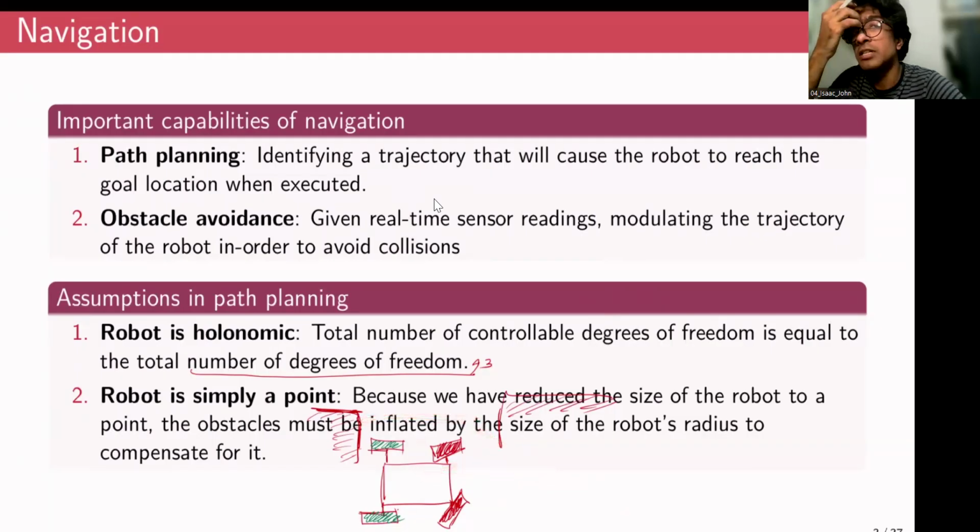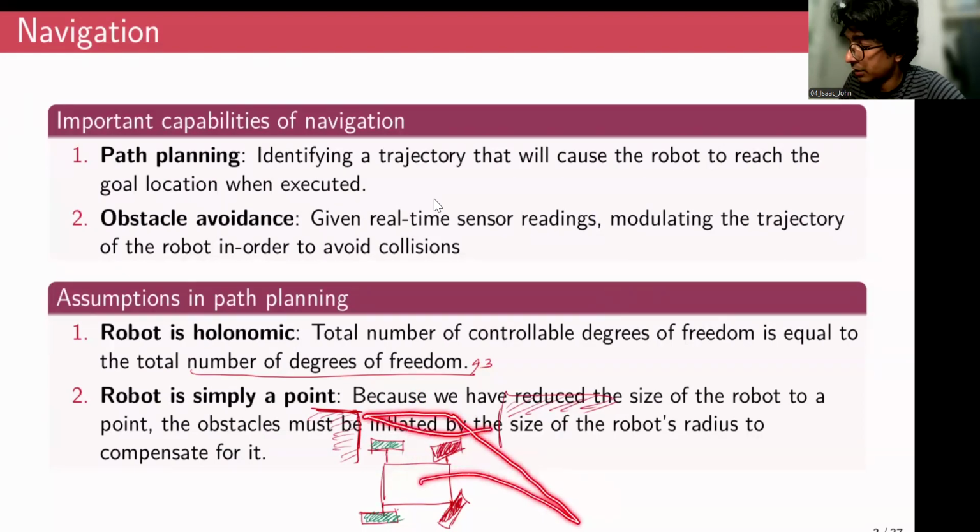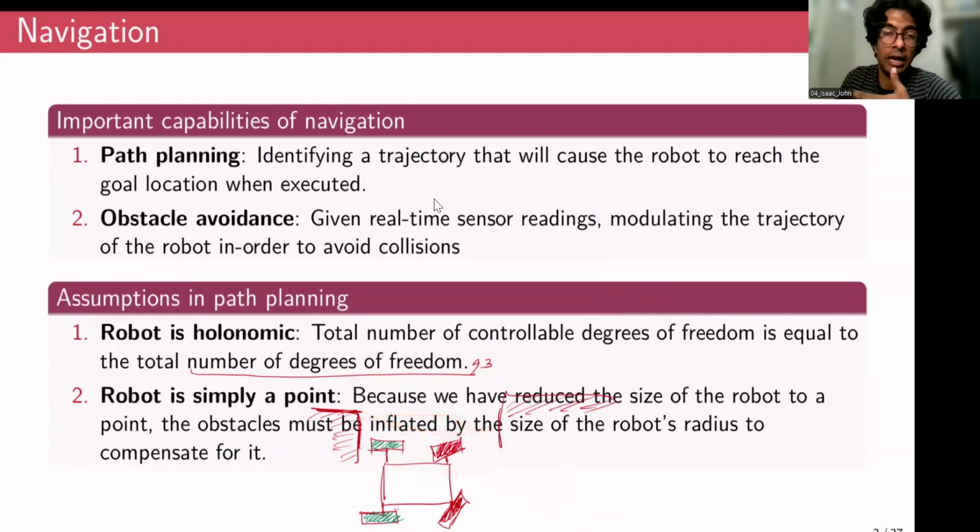So it takes multiple steps for a non-holonomic robot to achieve some specific position within the space. But a holonomic robot can simply slide laterally just like that. One simple swift motion can achieve the same result. But a car has to go forward like this. It has to come backward. Then it has to come all the way. Then it has to straighten so that it can be aligned.